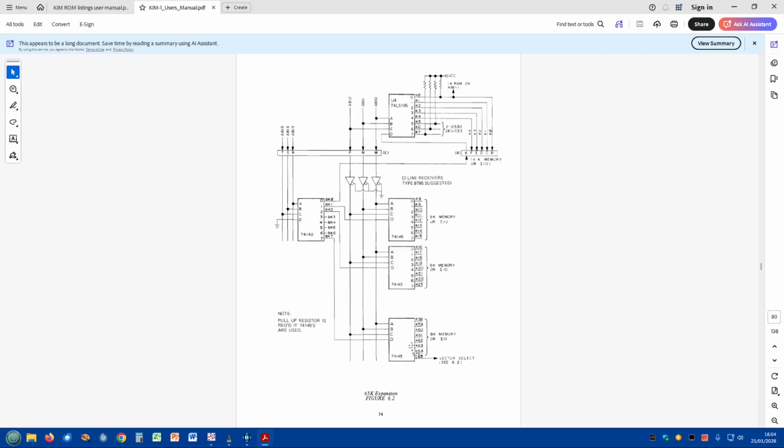You can keep doing that all the way up to the top, so there'll be 64, that's numbered wrong, got that numbered wrong now. There'll be 64 possible different decoder signals up to K63. It won't be a 64 and 65. I'm not sure what they're doing there. There are a few mistakes on the documentation I've noticed. All the memory chips are numbered around the wrong way. And some of the pins on the 6502 are labelled wrong.